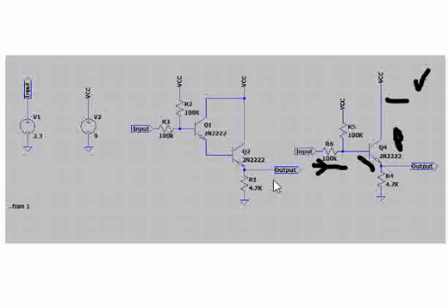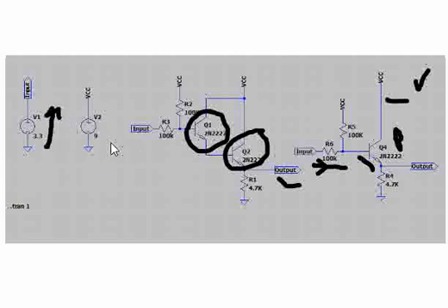If we come to the Darlington pair circuit, we can see the first transistor and then the second transistor, followed by the output connected to the load, and the input current is the same. Here the input is given from a fixed DC, and the collector supply is given as 9 volts. Again, this depends on what transistor you select. This is a DC circuit. If you have an AC input instead of a DC, you will have a series capacitor here, which helps for coupling.